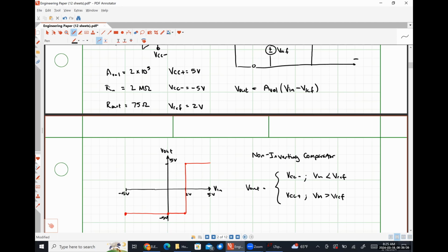That would fry it. But instead, we could use a zero crossing circuit like this to say, well, now our voltage is high, so we effectively know what our phase angle of our voltage is going to look like by time stamping when this transitions from low to high.